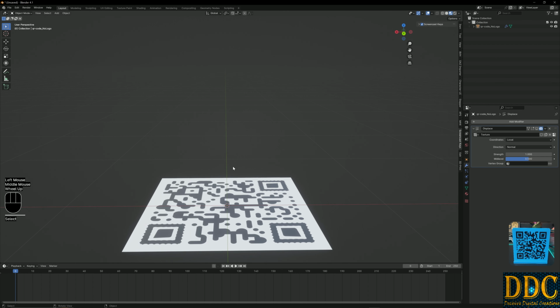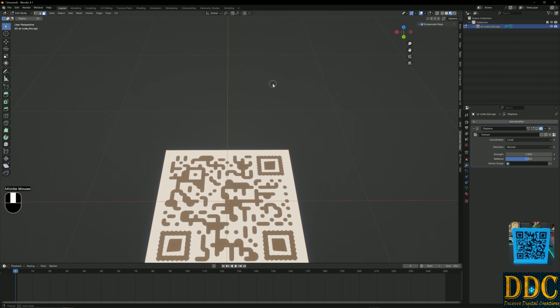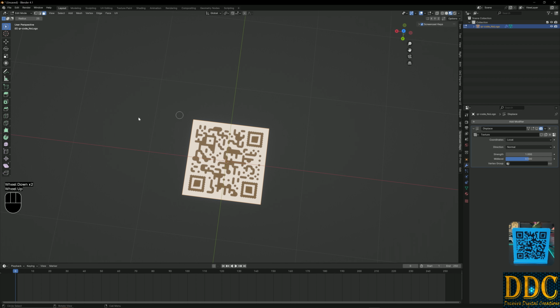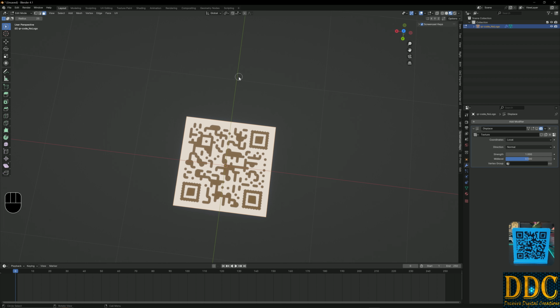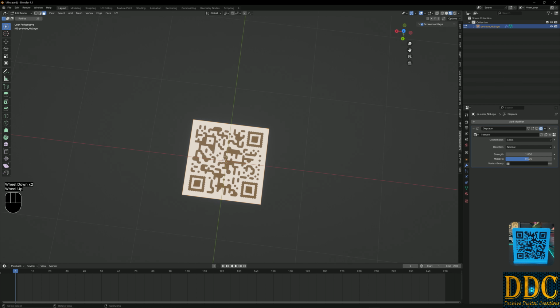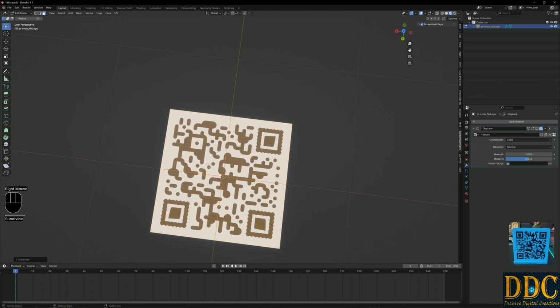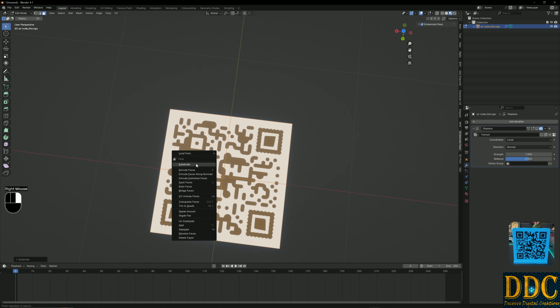Because what we're going to do is select our object, and hit Tab to go into edit mode. Now mine's highlighted yellow. Most of the time that's how things go in Blender, so you know you've got it selected. If you don't, hitting A will select everything. If you have another object and you're in object mode, it's going to select all objects. We just want this, and we're going to subdivide this by right clicking, subdivide, and we're going to do it many times.